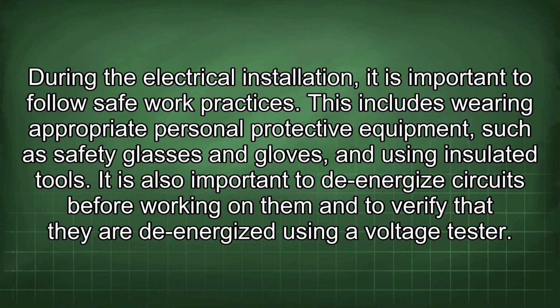During the electrical installation, it is important to follow safe work practices. This includes wearing appropriate personal protective equipment such as safety glasses and gloves, and using insulated tools. It is also important to de-energize circuits before working on them and to verify that they are de-energized using a voltage tester.